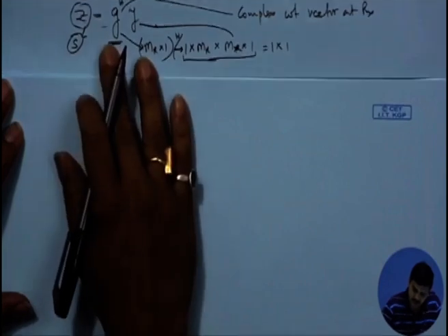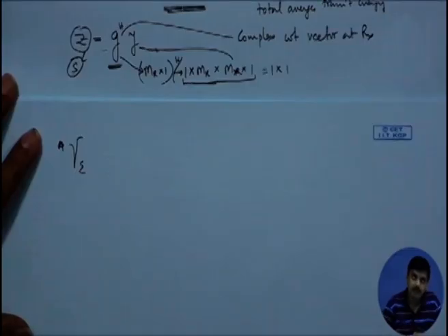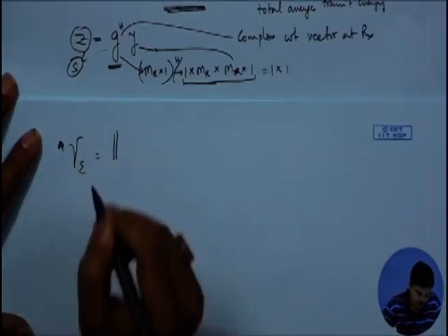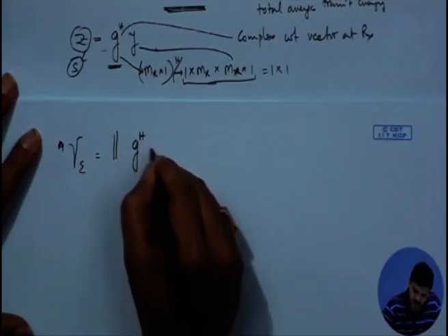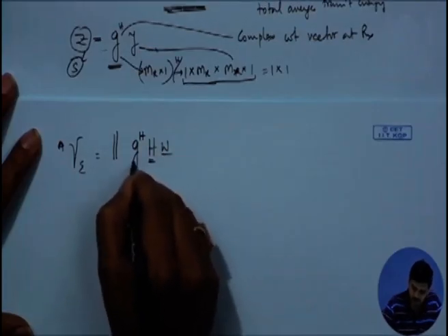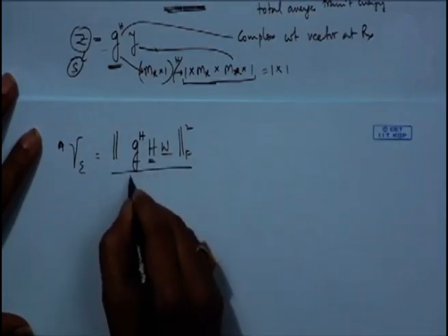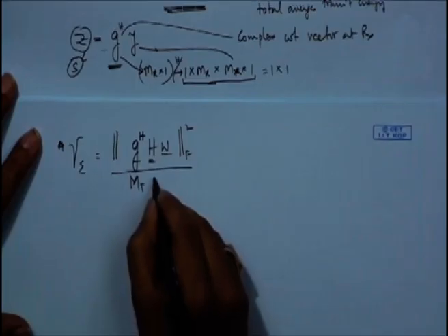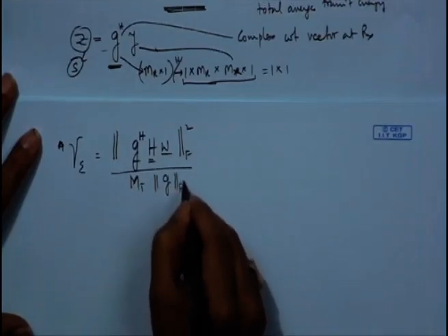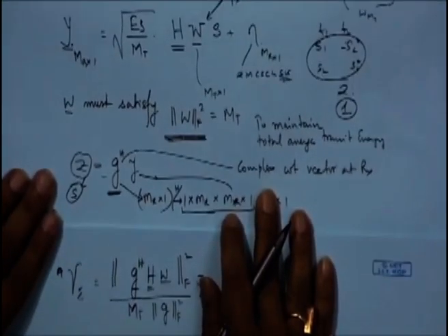So what we do is we have to maximize the SNR, as we have said. The expression of SNR, which is gamma combined, we put like this: it would be the Frobenius norm squared of G Hermitian H W, divided by MT times the Frobenius norm squared of G, and you can guess why I am doing this, because if you look at this expression,